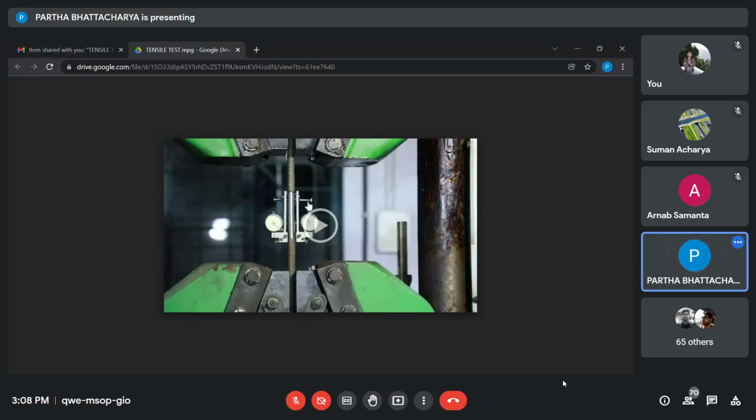This is an extensometer. This is one end of the extensometer, this is the other end. The two ends of the extensometer define the test length, or L0. This is the test length. Now once this is pulled apart, what will happen? There will be a change in the length. So the relative distance will start changing. There will be delta L, that is elongation, that you can measure. From that, you can measure the elongation of this specimen for each load step.